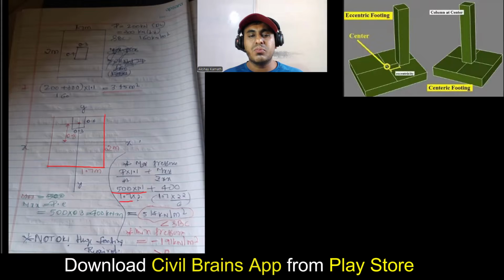So that is why I've taken 1.7 into 2 here. Okay, fine. So then next is Mxx, that is moment in xx direction. How much is moment in xx direction? It is 400 kilonewton. So I have written 400 into Zxx.